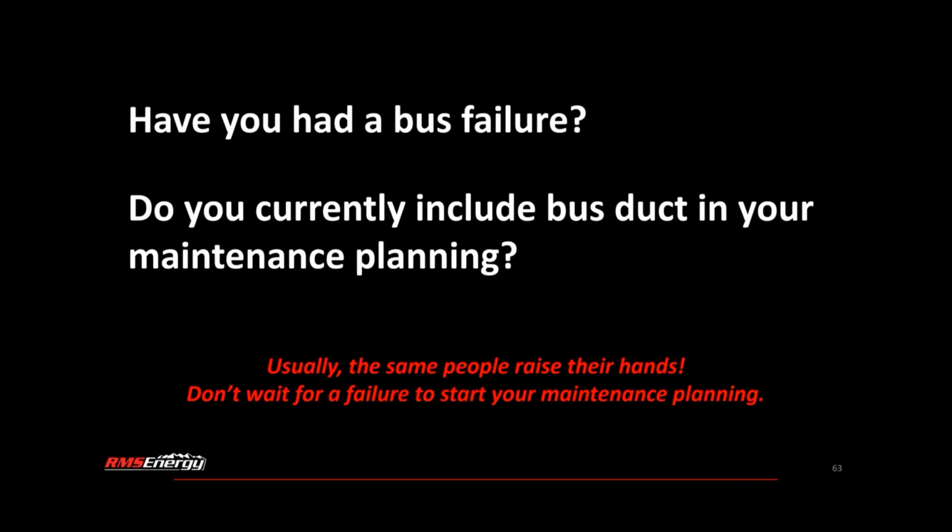Yeah, well, the one issue that keeps showing up too is that since 2019, GE did a generator repair for us, and since then we've been noticing our PD levels going up and up and up. Our IRIS is convinced that if these levels of PD were in the generator, there would be an issue with the generator and we'd have major problems. But they're convinced it's something along the isophase bus itself. That's all we've seen, a trend going up in PD the whole time, and now we found this hotspot recently, so we're just not sure where we're supposed to go with this.